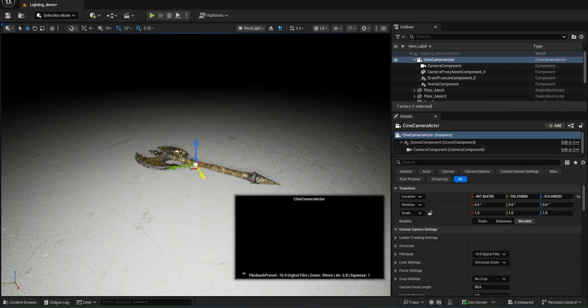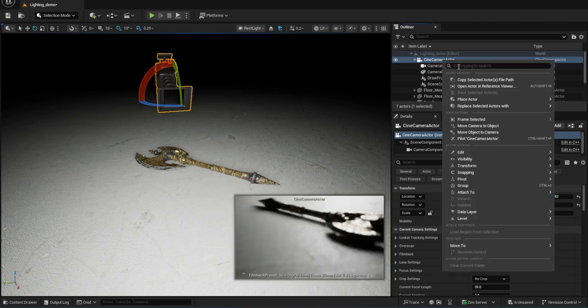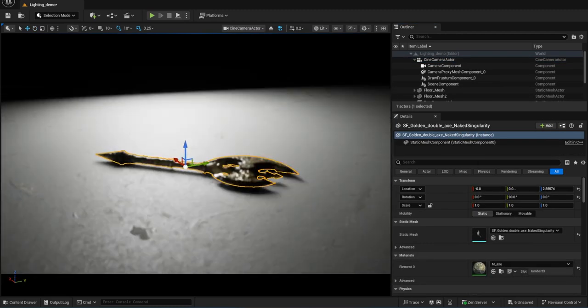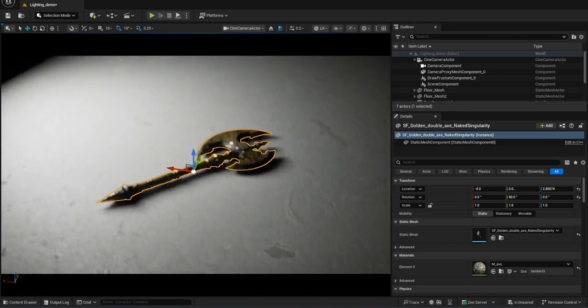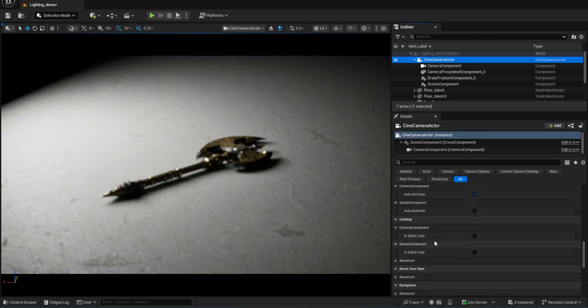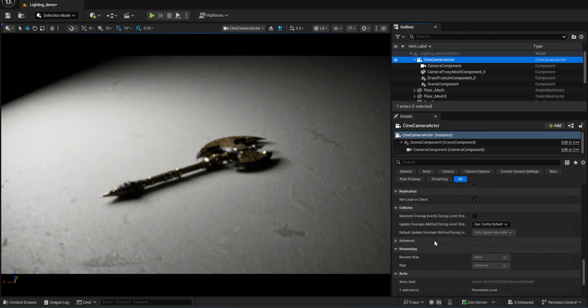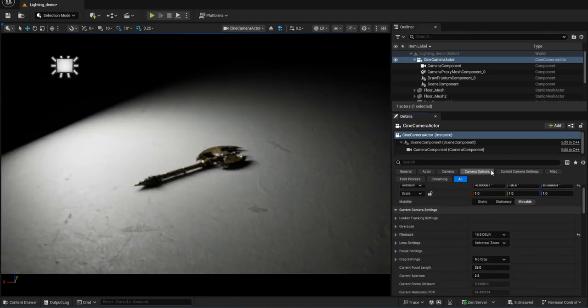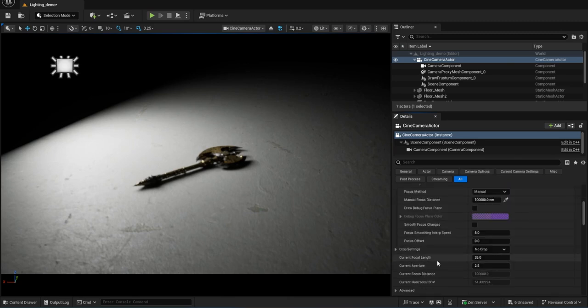Okay, now we have our camera here, push it up. Same thing, we can right click and change to pilot camera. Click on the X, press F, and let's position it in a presentable way first. Change our camera setting. Let's click on camera, and we will change our focal length first. We will use a DSLR setting. Under current focal length, we will set it a bit higher because this is quite a close-up. So maybe we choose about 120.